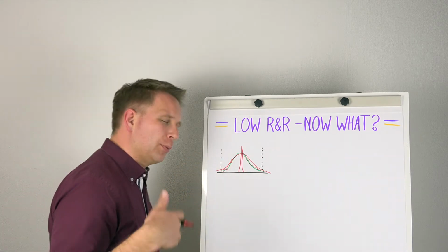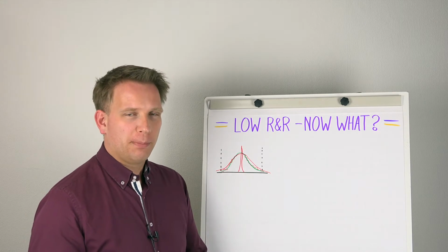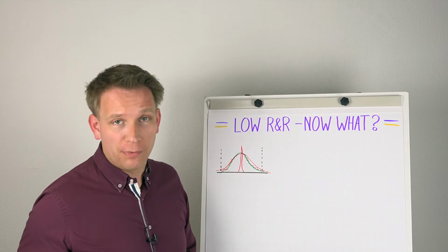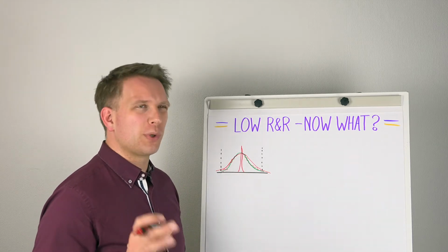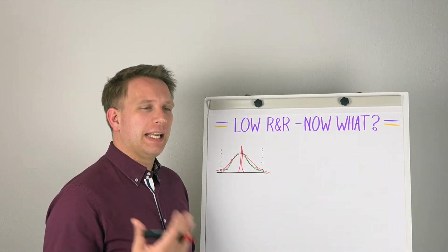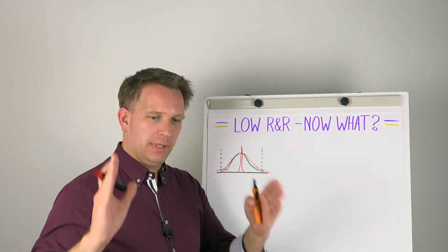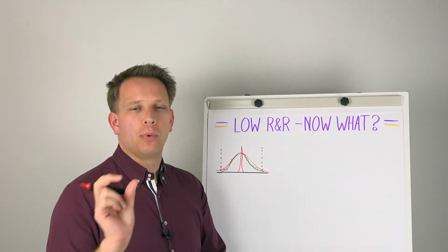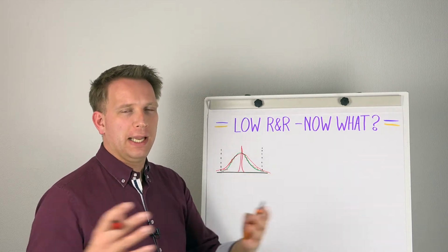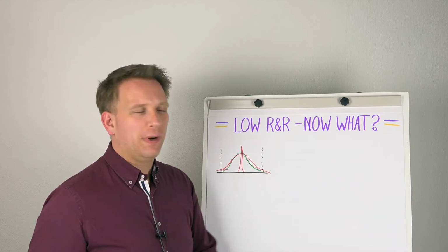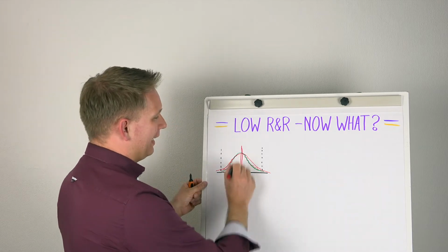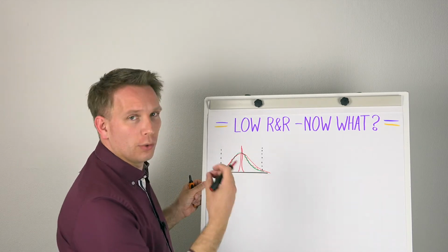And there's a bit of debate whether you should use the observed part-to-part variation for this testing or you should use the spec. I would actually say use both of them, but you usually use the smaller one. In the end, if you have a set spec range, you anyway want a tenth of that, but also if you have a product range, you need to find it over there. Anyway, those are the details more for the how-to-do-an-R&R video. This is the ideal system that you see.